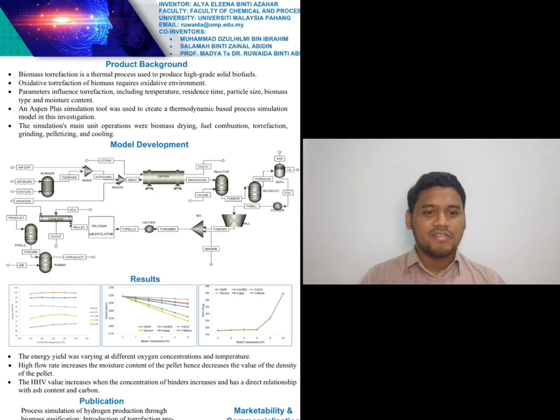The process starts with 2 streams that go to the burner, which are the air and the net gas, with a fixed flow rate. The Gibbs reactor was used to burn those components with the air. The design spec function was set to create a flue gas to the dryer portion, and the hot gas was diluted with air before drying to obtain the set point temperature.